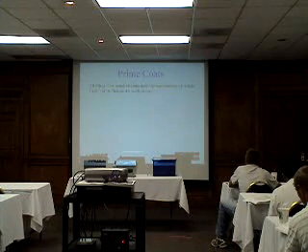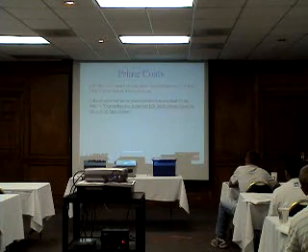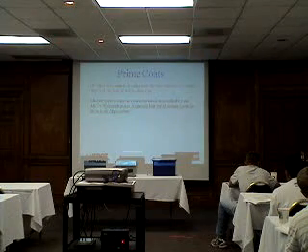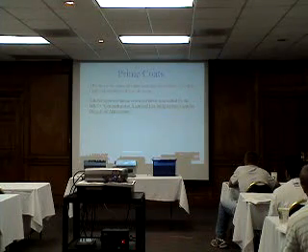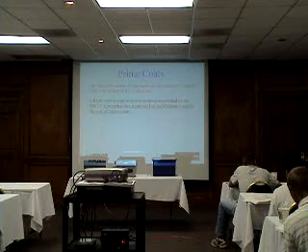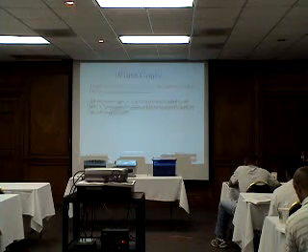Prime coat must meet the requirements of Article 1020-3. There is a list of the approved sources of prime that we looked at this morning when we looked at Section 2. There are only 4 approved sources on that list at this particular time. Again, you need to check with M&D if you don't have one of those particular brands that were on that list.